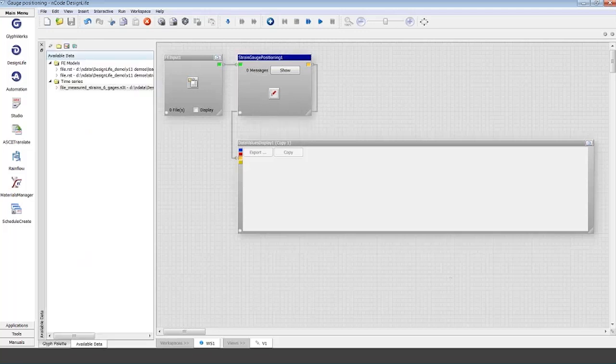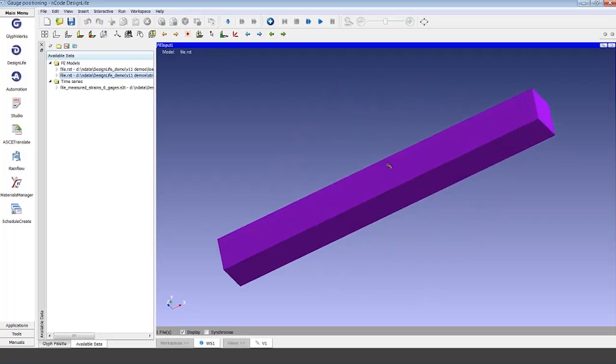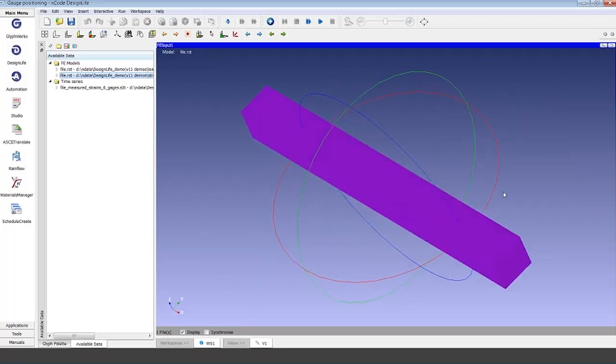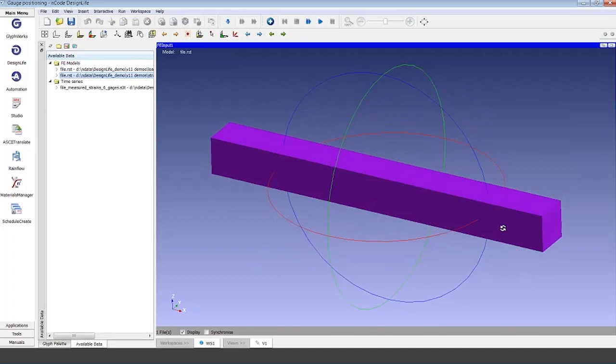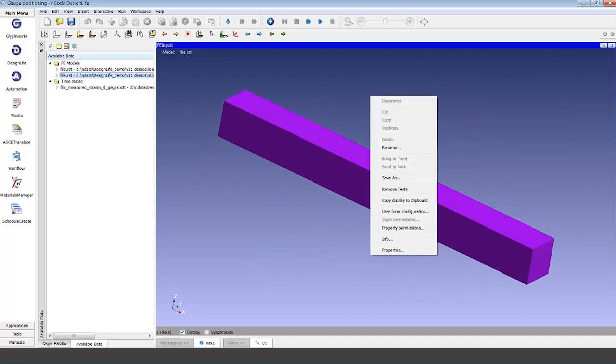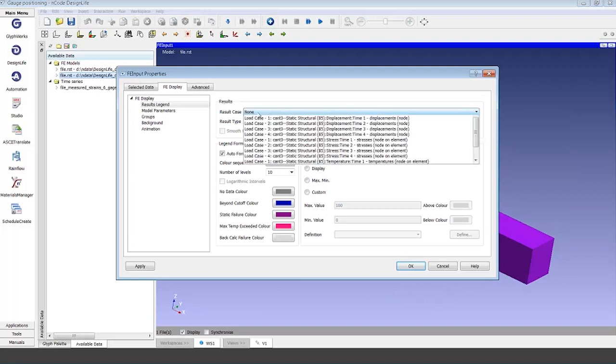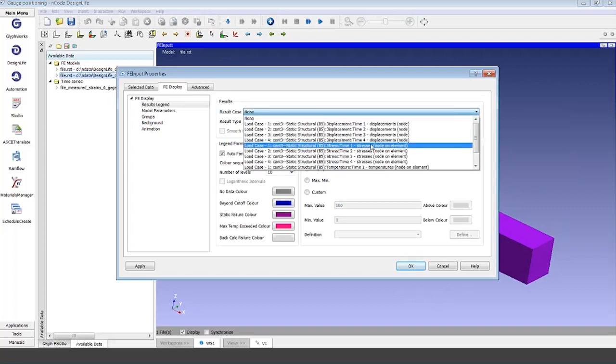I have my finite element model here that I need to go grab. Let's put this one in here and take a quick look. This is not very exciting geometry, I'll admit that, but it will save time today in terms of running quickly. We'll file this under learning to walk rather than running. In terms of degrees of freedom of loading on this thing, I've solved this, I've done a unit load input for four separate degrees of freedom of loading.